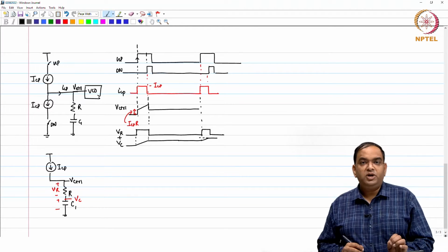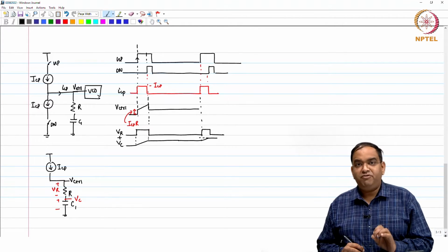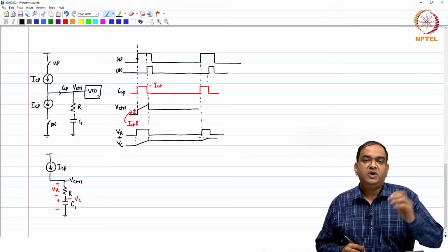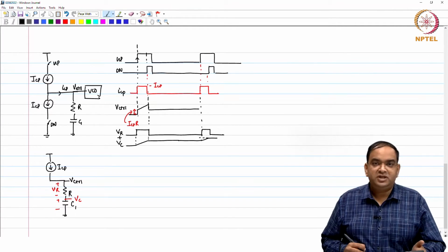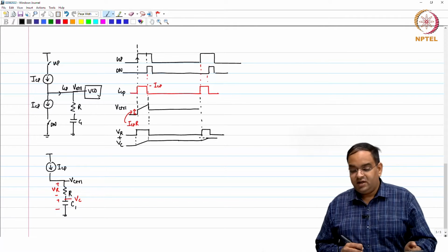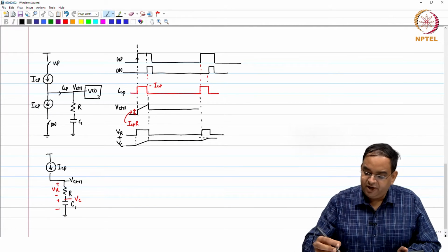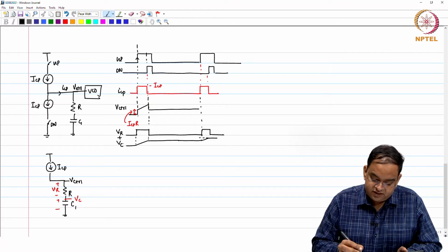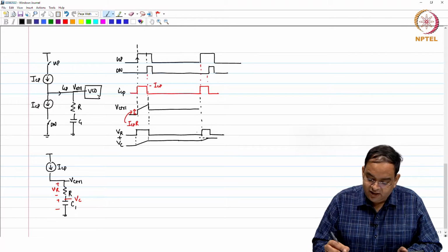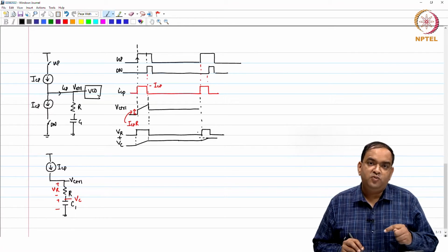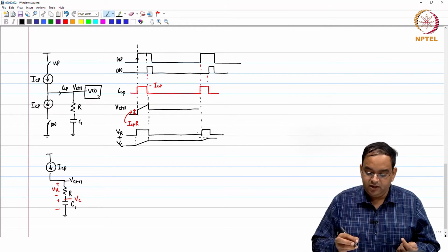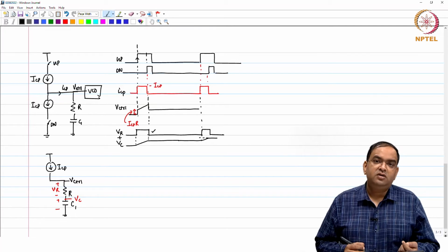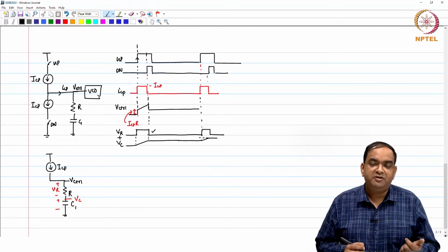So, the control voltage of the oscillator changes every reference period for multiple reasons, right, whether you have phase error, or there are some problems in the charge pump and other things. Those things will happen. So, because of this change in the control voltage at the reference frequency, you modulate the frequency of the oscillator with VR, like a pulse waveform.